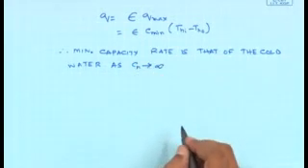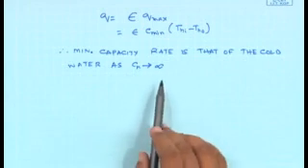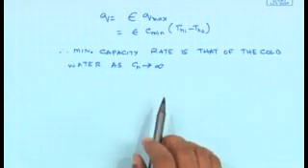The capacity of the hot fluid, since it's steam condensing on the outside, will obviously tend to infinity. So therefore we are dealing with a situation in which CR is equal to 0. So that would allow us to use a simple relation between epsilon and NTU, and since NTU is known, we should be able to calculate epsilon, and from epsilon we can calculate Q, and from Q we can calculate TCO. So those are the steps which I am going to follow one after the other.